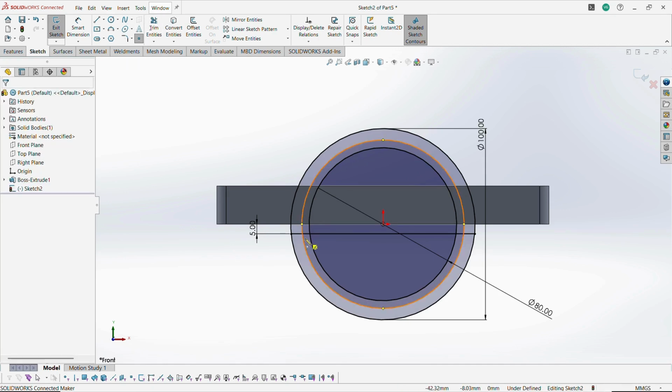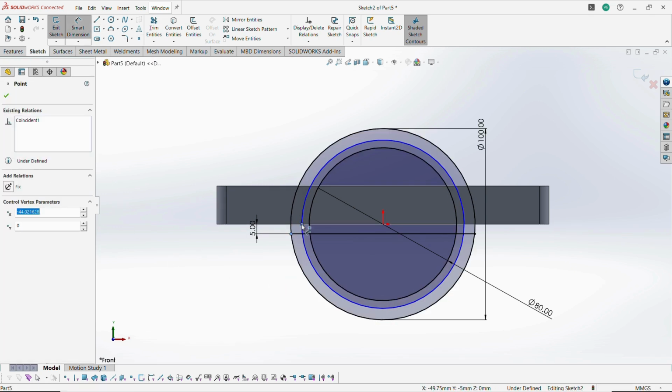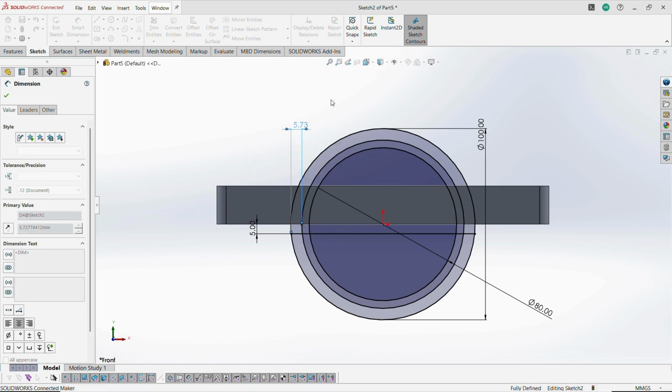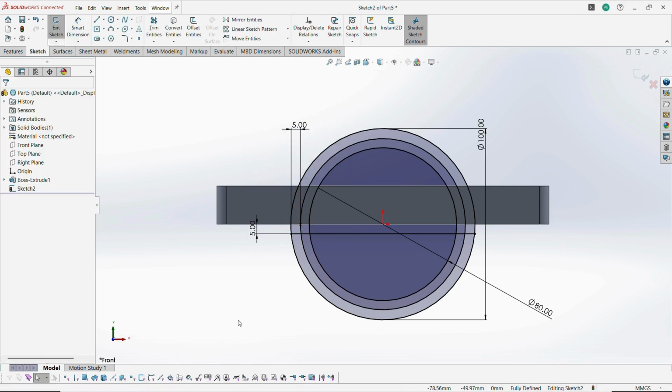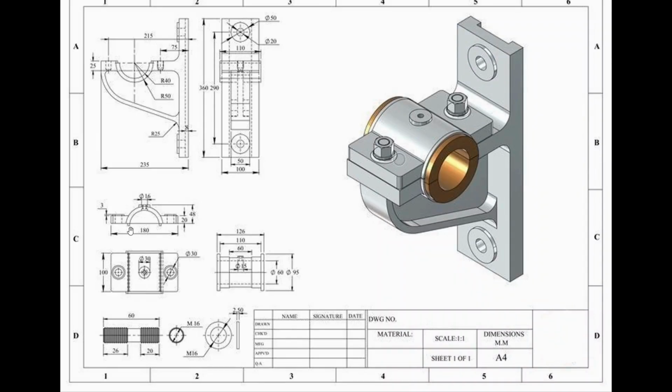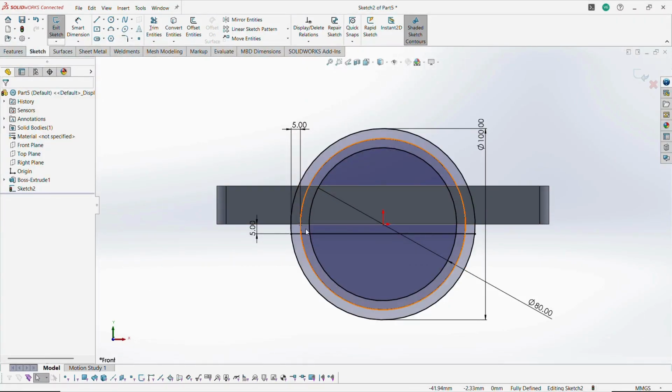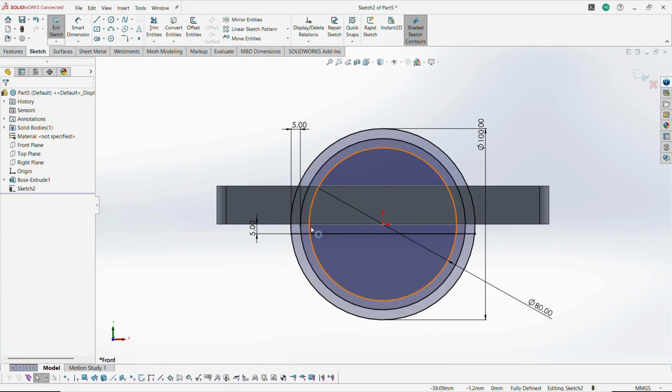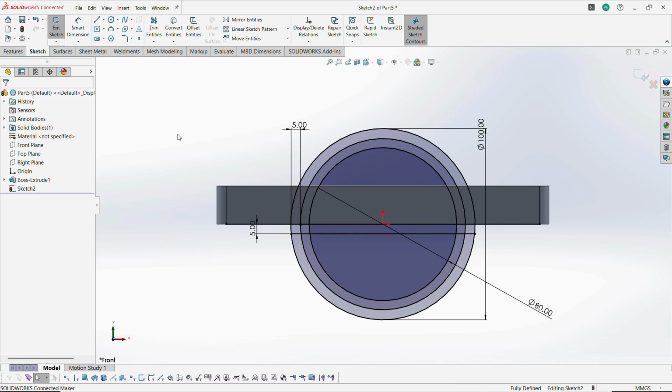So using a point placed at the center of its location, then choose the smart dimension from the point, initiating the horizontal dimension of 5 mm. Look at it, three different circles, one central line. Let's achieve this recommended area. Instead of that, let's draw another line profile horizontally. Select this horizontal edge and form it into a line by using convert entities.